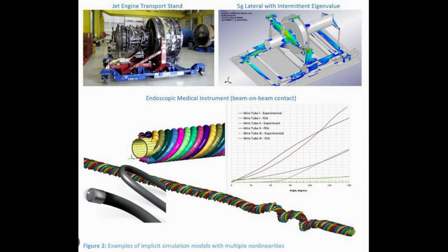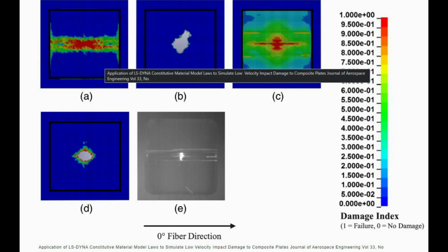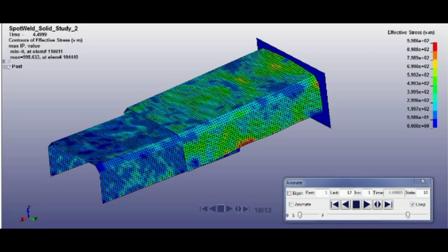LS-Dyna incorporates damage initiation, damage growth, and interaction of multiple damage mechanisms. Commonly used damage models include MAT_072, Modified Johnson-Cook damage, for metals, and MAT_58, Composite damage, for composite materials. In summary, in LS-Dyna simulation, a failure model determines when a material is considered failed based on specific criteria, while a damage model predicts damage evolution within the material. LS-Dyna offers various material models and options for accurate simulation of failure and damage behavior.